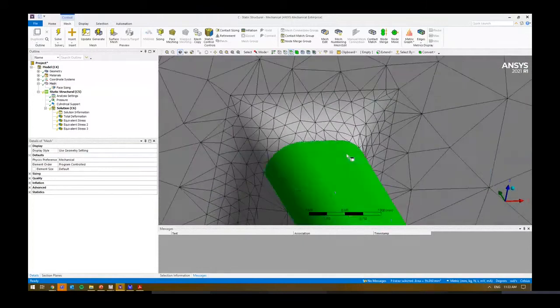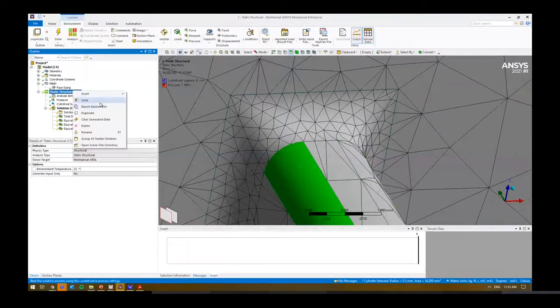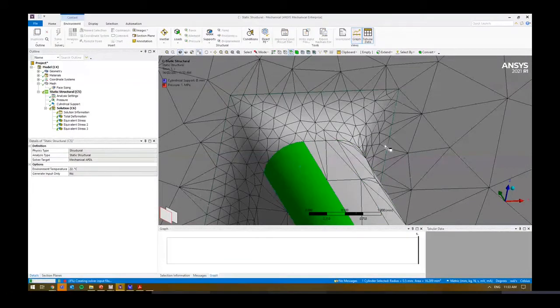Now, you'll notice, by the way, straight away there's a pretty large transition. So in reality, I probably want to go back and either make some changes, make the mesh locally around here finer. I can use things like a body of sphere of influence if I wanted to as well. Right, previously, the stress around there was around 500. And we can have a look at the stresses.